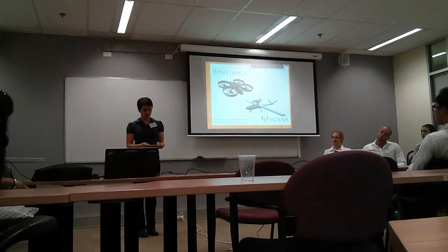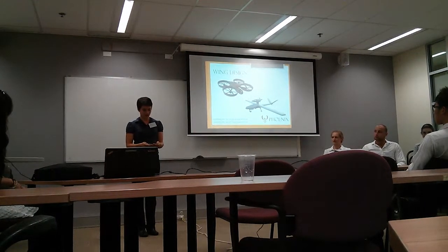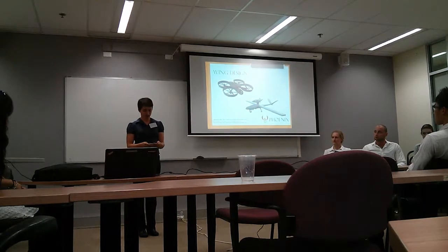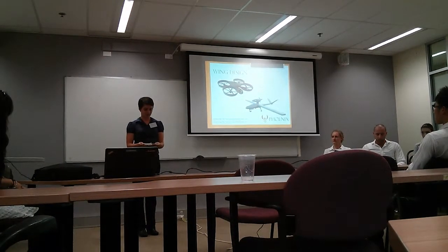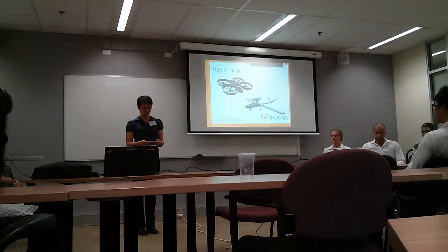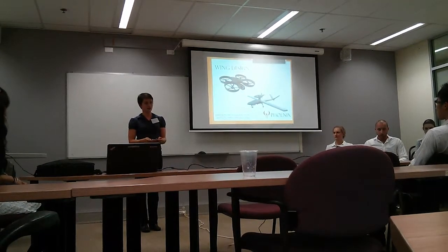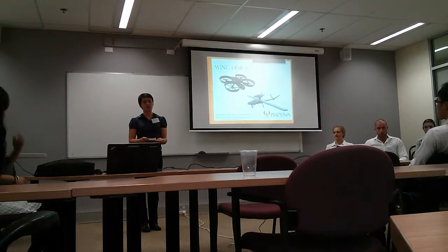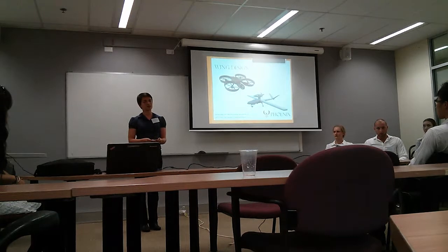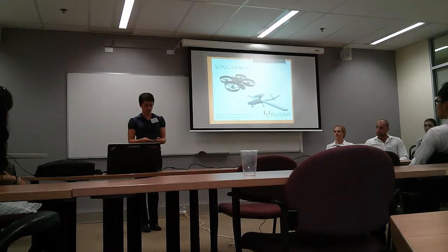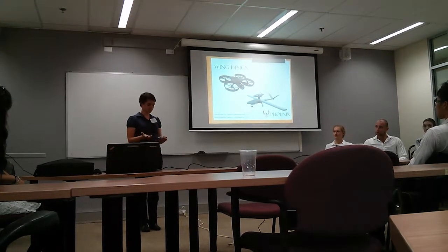Since our UAV is for providing up-to-date surveillance information of bushfire-affected areas, maximising the speed, range and height is desired. In addition, since the UAV must be capable of carrying surveillance equipment, we require a UAV that can handle a relatively heavy payload. For these reasons, the Phoenix team recommends the use of a fixed-wing UAV for this project.